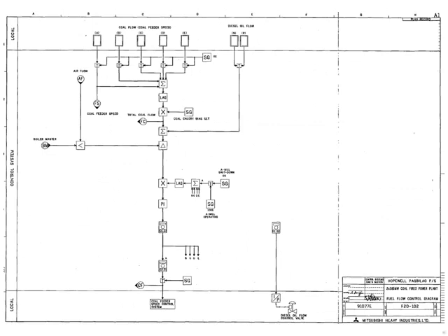Fuel flow control is designed to control the in-service coal feeders as well as the warm-up fuel oil flow. Under a load transient condition, the fuel control signal changes the coal and the fuel oil flows. However, it is always set to be below that of the airflow to prevent a fuel-rich mixture.